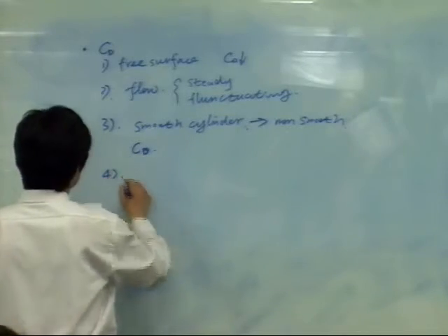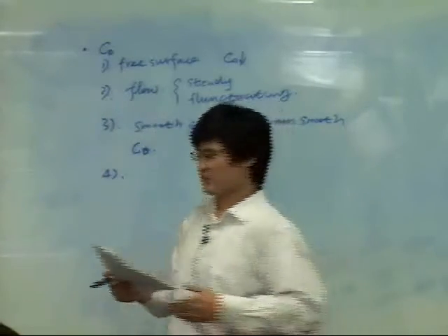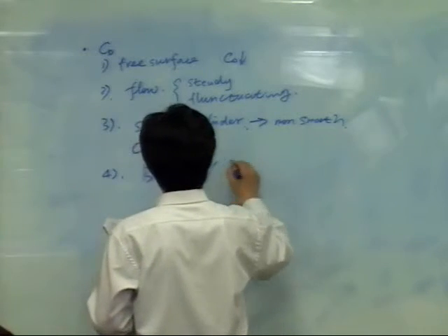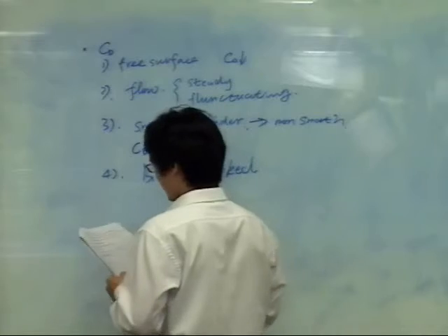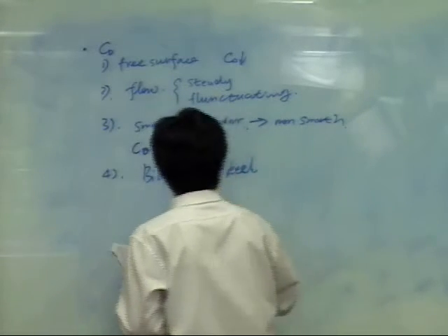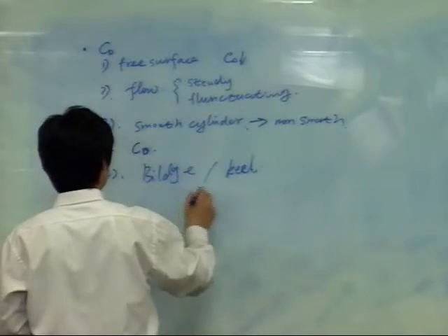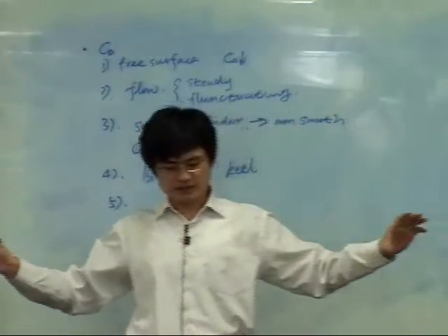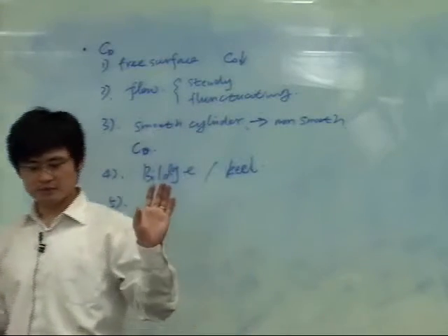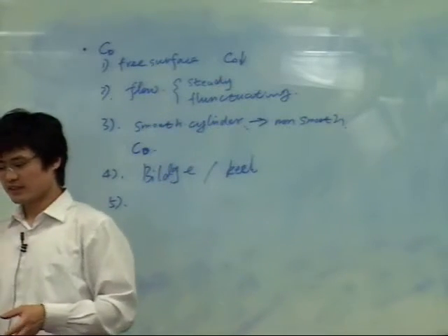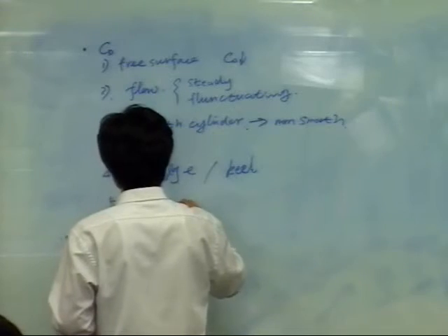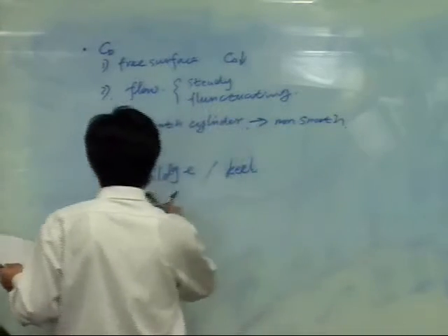And for stability considerations, we put a bilge keel and skeg on the body. These have effects on the CD. Also, even if the shape itself is long, at the bow and the stern the two-dimensional assumption is not really valid, so we have a three-dimensionality effect.